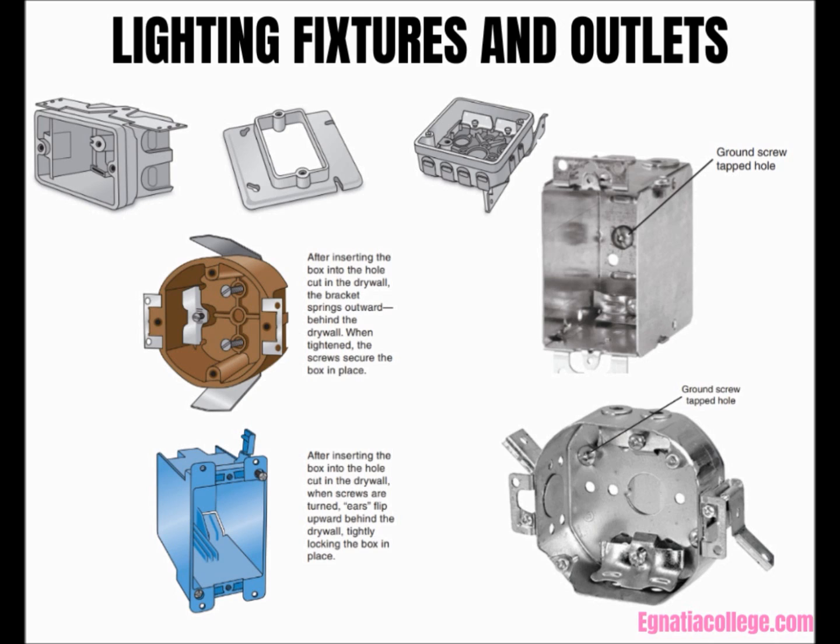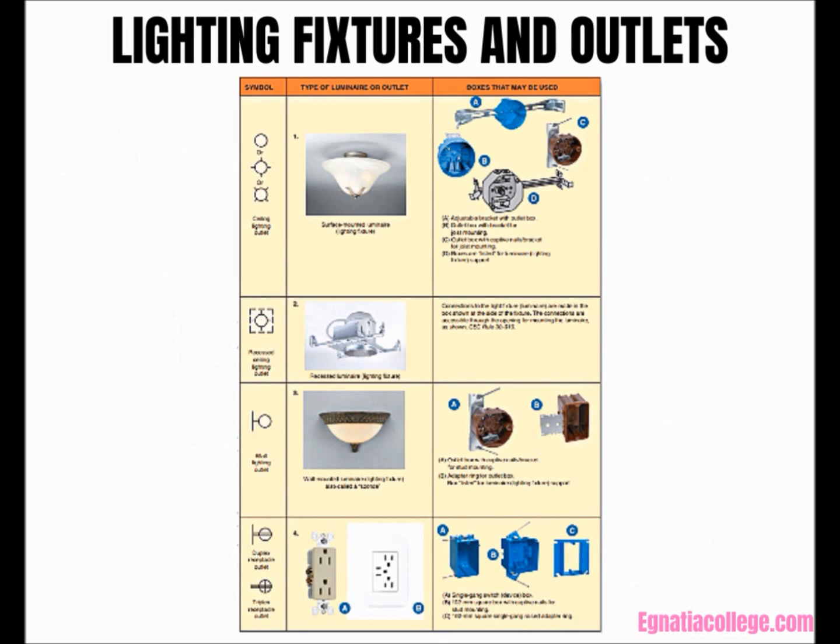These switch boxes are made of steel. If the owner selects fixtures before construction, the architect can specify these fixtures in the plans and/or specifications, giving the electrician advance information on any special framing, recessing, or mounting requirements. This information must be provided in the case of recessed fixtures, which require a specific wall or ceiling opening.